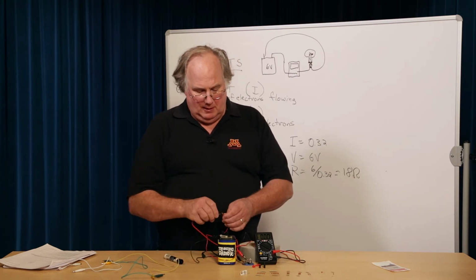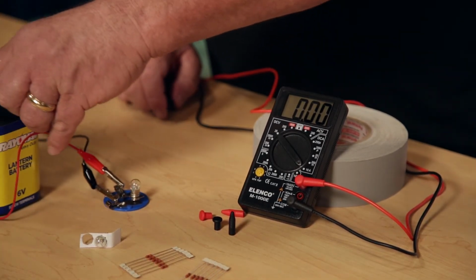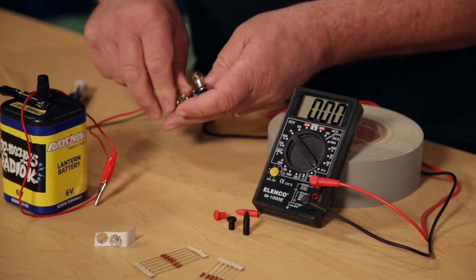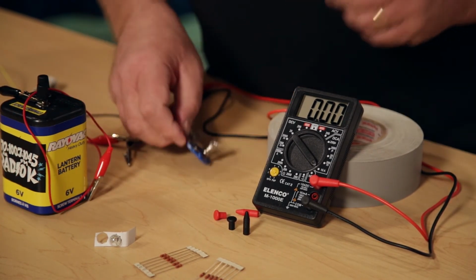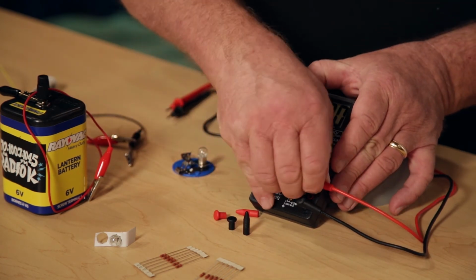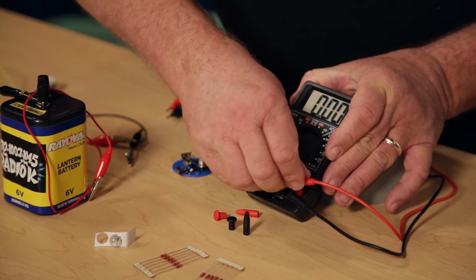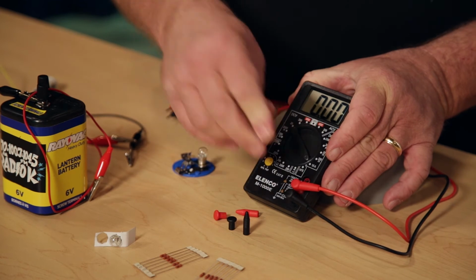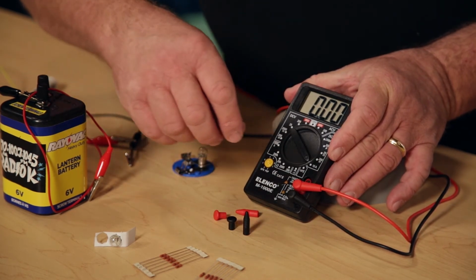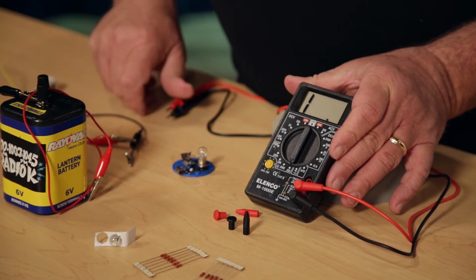To use the meter to measure resistance, we take our circuit and move that away. Take the bulb and measure resistance. You have to put the probe back at the R input, like so. We have to flip the meter over to resistance, which is down there.